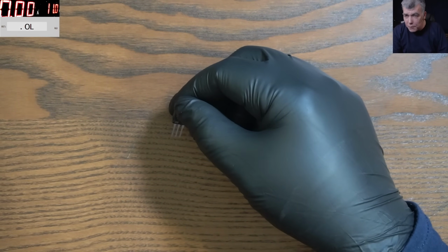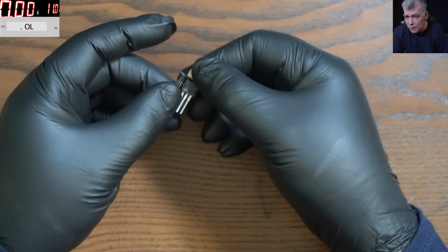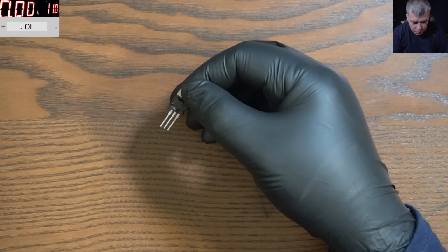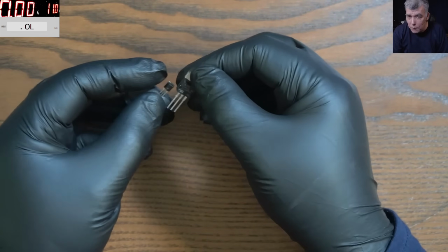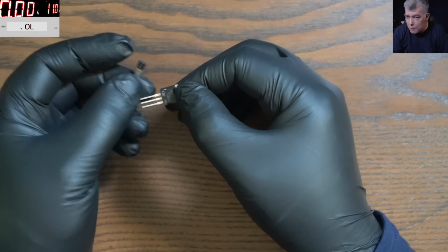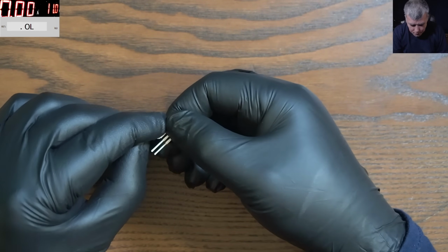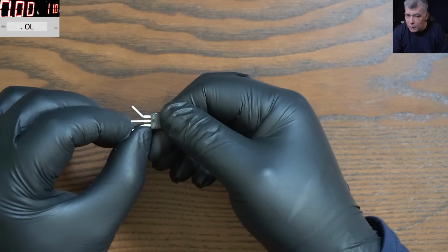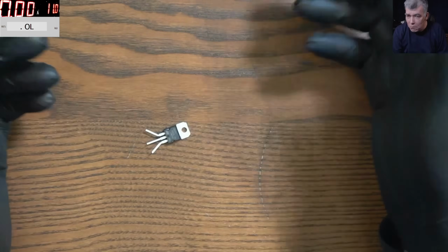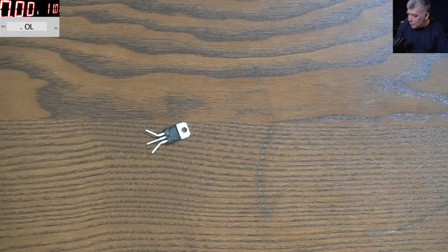So the difference between transistors is about how much current they can carry. The small one doesn't carry that much. The big one will carry more. The other difference is the amplification factor, which is higher on the small one, but we'll speak later about the amplification. First of all, how do you check a transistor? We don't know which is base, collector, and emitter. Very simple. Let's get a multimeter.